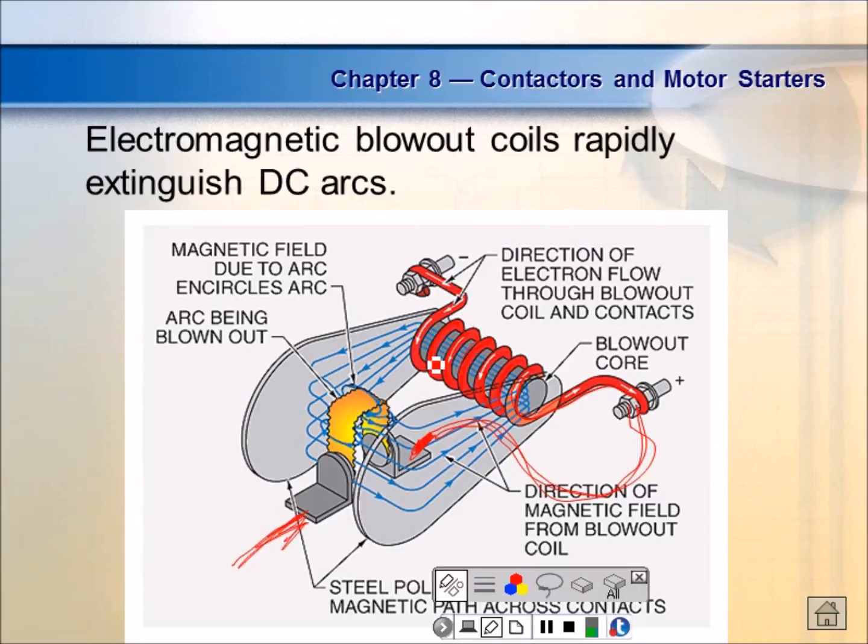And when I put voltage to a coil, then I create a magnetic field, right? I showed y'all my little electromagnet right here. Okay. So this field builds out, but the contact is closed. Okay, y'all understand that? When the contact opens, then the field collapses within this coil. So we set up a magnetic field between these two paddles right here.